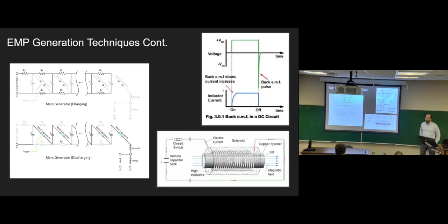Yeah. So what if on your Marx generator circuit down there, instead of resistors, they were inductors? When you created that spark gap, would their resistance to the current change negate your sudden spike in voltage? So if they were inductors in this stage, and they'd stay that way, they would act like a low value resistor, because it's just technically a DC steady state.